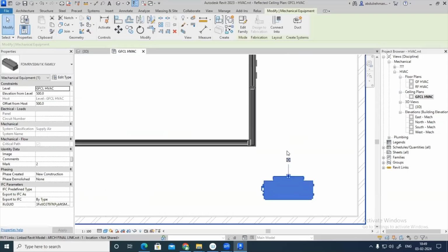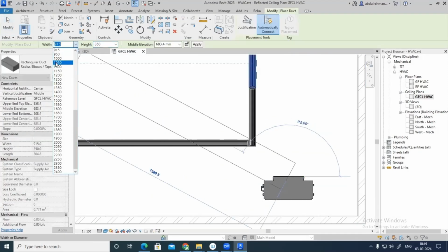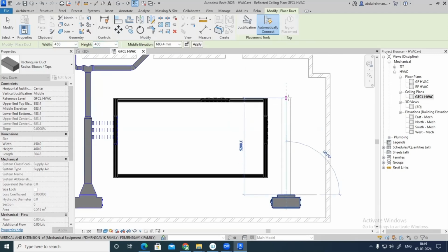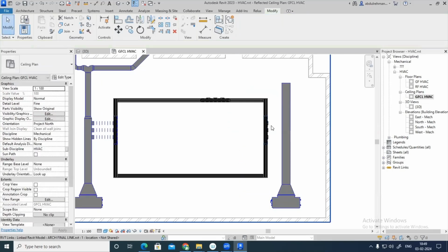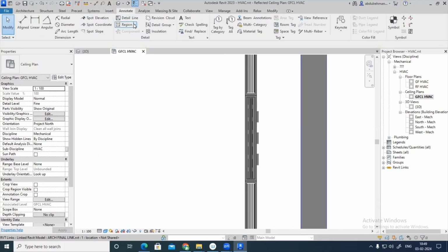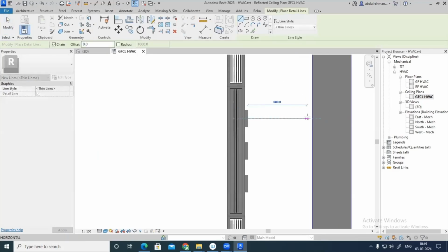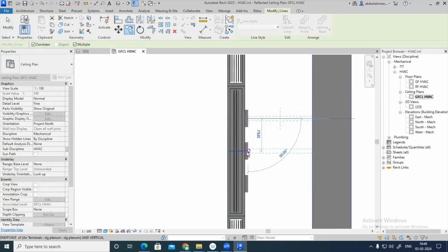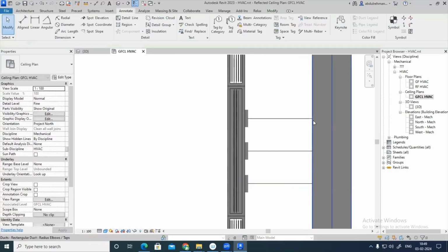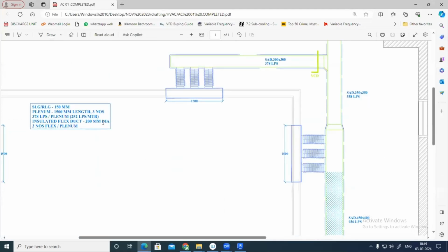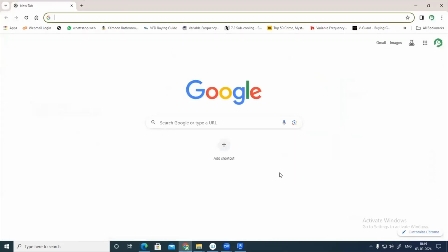Okay. Select this one. There is 450, 400. That's to extend level here. Now this one we should connect this plenum. Just go to the insert, sorry, annotate option. Let me make this one. Copy this with respect to there, here, and here. So I need a collar of 200. Now this is also 200 dia flexible duct. The same for all these plenums, 200 dia.